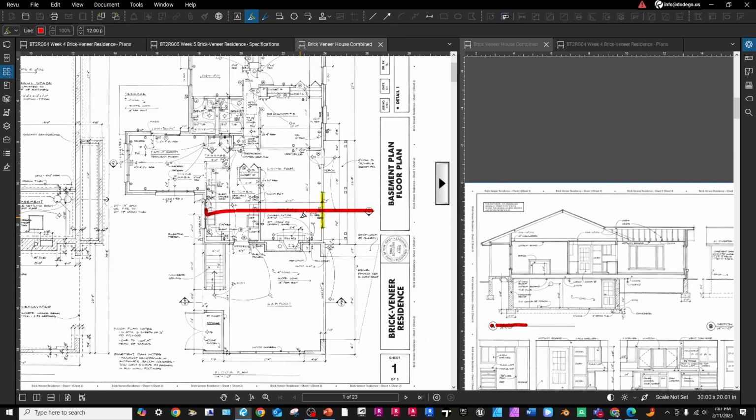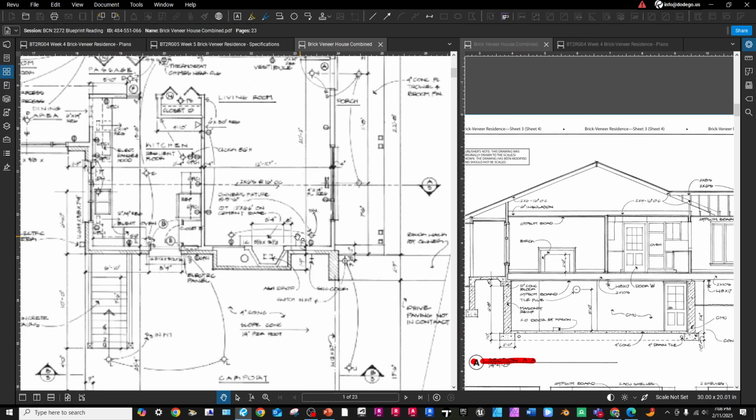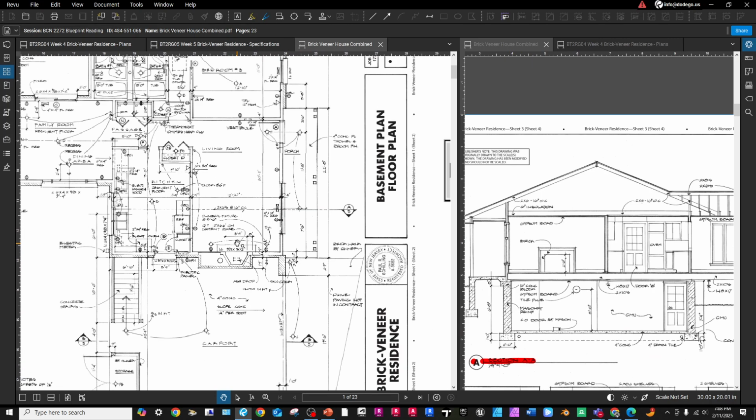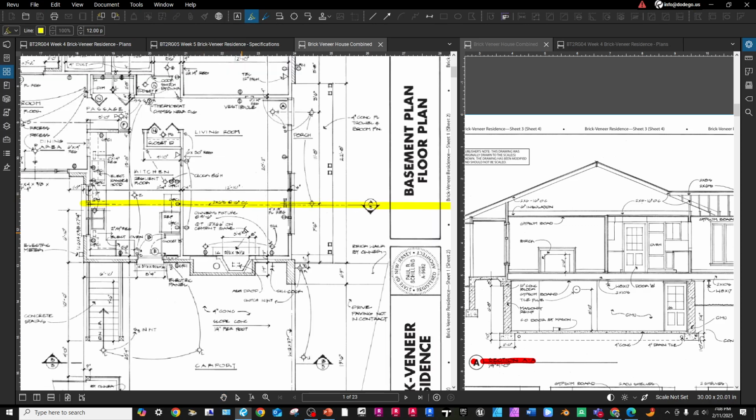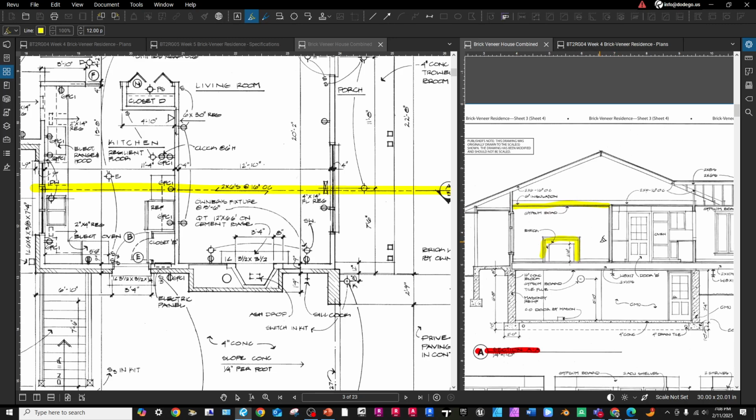So cutting through that whole building as a building section, you see everything south of that line looking downward. This is called your building section. That building section is at 1/4 inch equaling 1 foot. Here we should see that brick fireplace, which we see here. That ceiling does have gypsum board to the top of that 2x6.